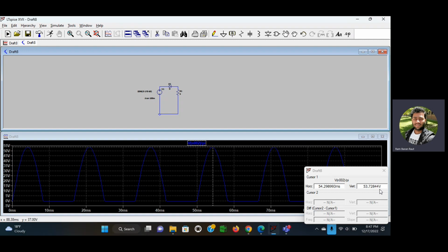We can calculate over here also: 169.7, which is the peak source sinusoidal voltage, when divided by pi, gives 54.0202 volt. Before we had 168.78, and dividing by pi we are getting 53.728. So this is the output voltage.